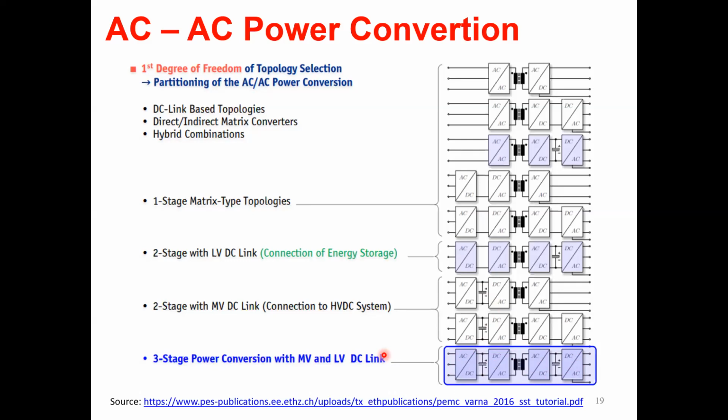considering it's a little easier to build. But of course it uses this electrolytic capacitor, and depending on the application it may either be large or small. So here, if it is a three-phase, it may be still manageable, but if you have a single phase system, then those electrolytic capacitors will be much larger.